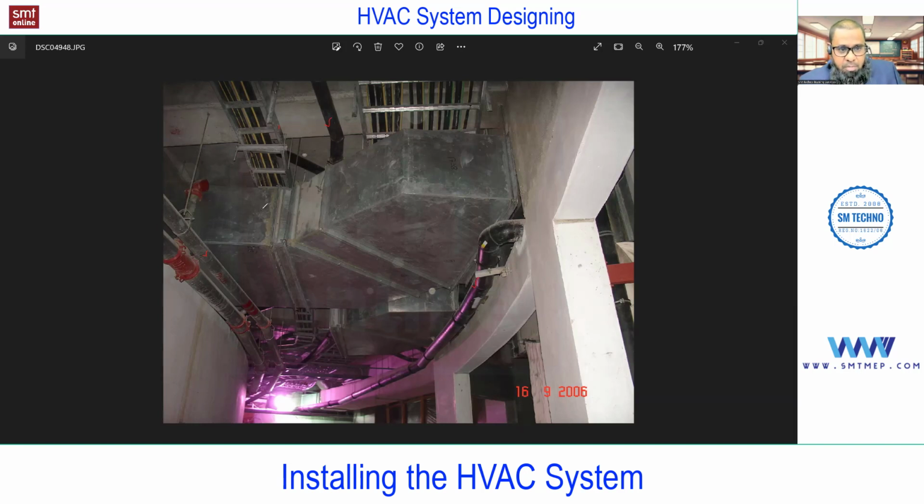So now we have an option for this duct. Remember, the height of the duct we are going to decide as per the available clearance, considering the clearance required for other services. And this is very, very important. And as an HVAC design engineer, this point, as I said, we'll discuss in chapter 6 point number 8. And this is related again to duct designing. If you talk about duct designing, most commonly we use rectangular duct. It can be oval duct, it can be round duct. We have advantages and disadvantages, but most commonly rectangular duct. And rectangular includes square. We are not calling a separate square category.